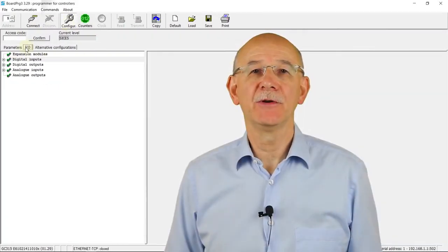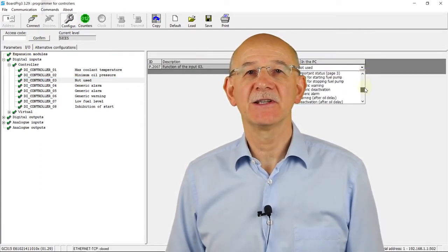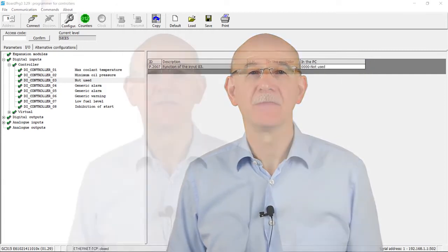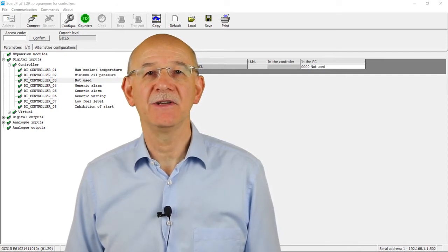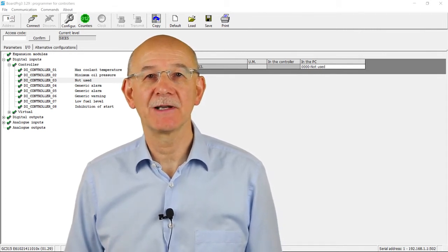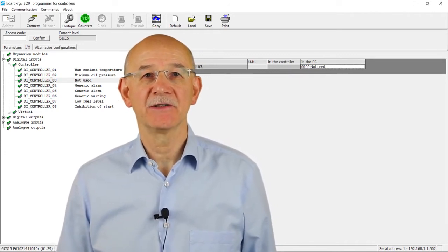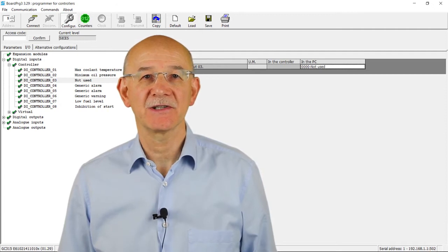More easily, the configuration can be made by the PC software G3, accessing the tab I/O and selecting digital input and then controller. Here you can find the 8 inputs plus the analog inputs configured as digital ones, if any. Selecting an input, it is possible to change the related parameters. If the function selector parameter is set to 0 not used, no other parameters are shown. Otherwise, a list of 3 parameters will be accessible.